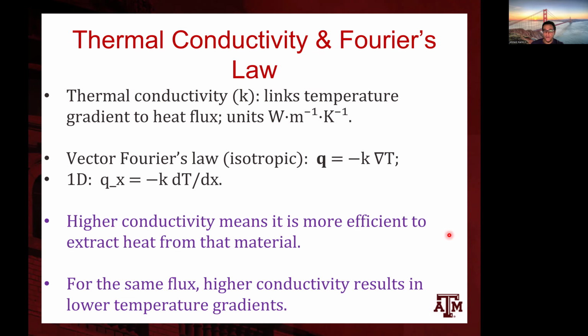So what types of laws and equations do we use to study heat conduction in solids? The most important material or constitutive law that we use is Fourier's law, which tells us that the heat flux is linearly proportional to the temperature gradient. So depending on the gradient of the temperature, the heat will transfer from high temperature regions to low temperature regions. So that's where this equation comes from.